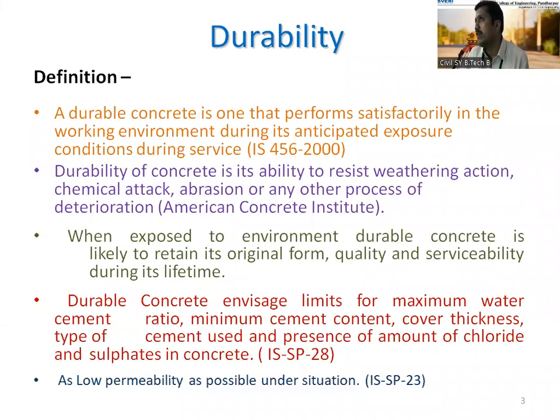which has been given in our IS 456. I will show you that table also. Because your concrete is exposed to different environmental conditions, like mild, moderate, severe, very severe, and extreme. These are some levels of environmental exposure conditions. Mild means room standard temperature condition is there. Moderate, maybe the temperature is more than that. Your concrete is exposed to somewhat more variation in the temperature.